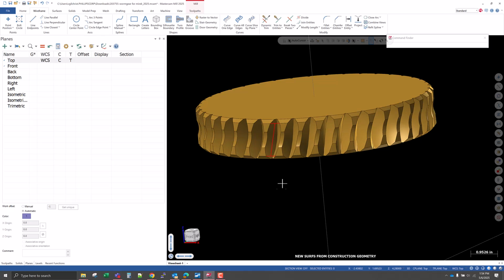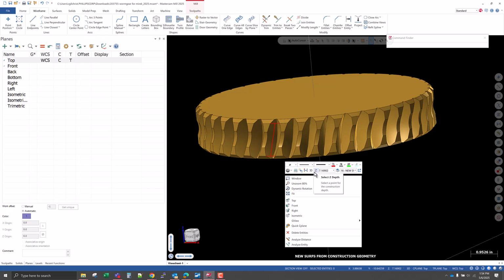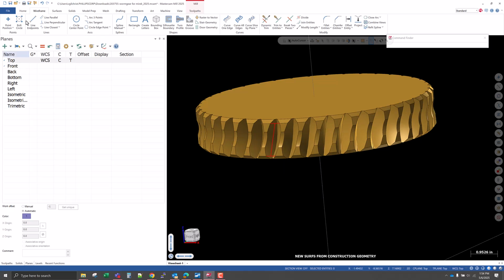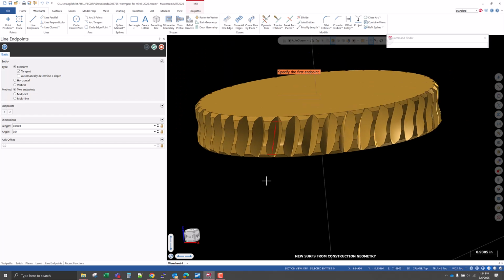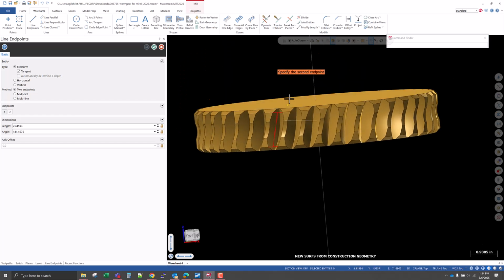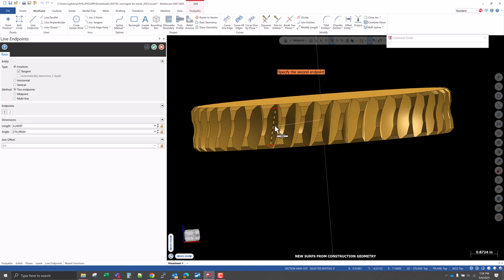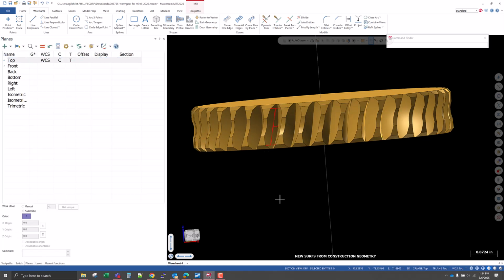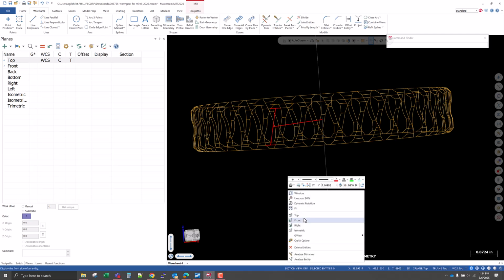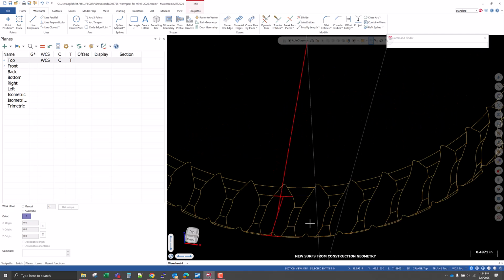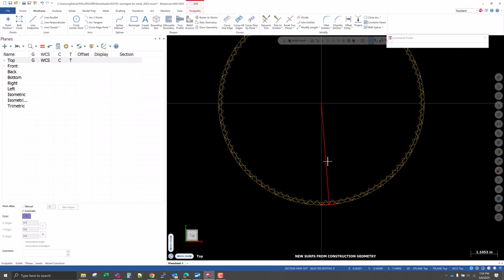And so if we're in the top view and we set a Z depth to the midpoint there, and make that 2D. I'm now going to draw a line by endpoints and hit O for the origin, which should be right at that height, and then M for the midpoint. And now, when we look at this in the top view, that should be our angle.